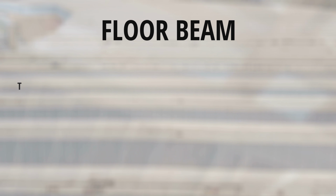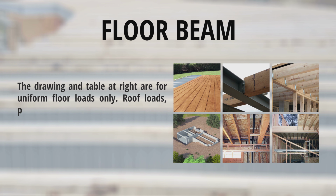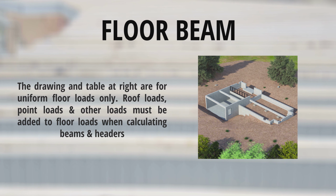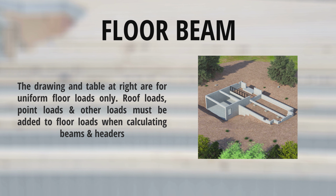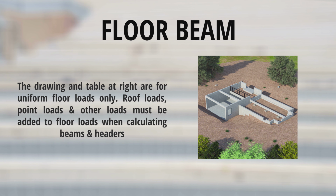Floor beam. The drawing and table at the right are for uniform floor loads only. Roof loads, point loads, and other loads must be added to the floor loads when calculating beams and headers. Let's take a look at the illustration. Crib and pony walls, beam spans, beam types, connections to foundation, wood beam or girder post connections.